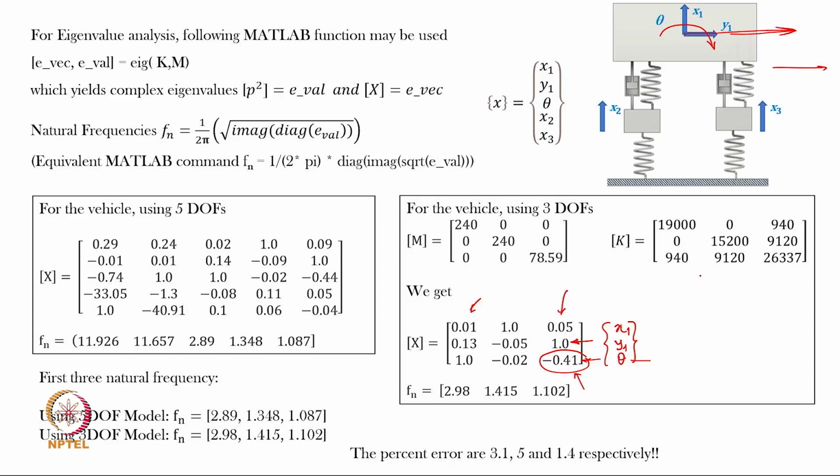I hope you recall that we discussed the mode shapes of a simple 2 degree of freedom system for one particular case when there were two masses connected like this, right. You remember that a spring here was K, this was K, this was 2K, this was M and this was M. So, what was the first mode? The first mode was defined like this. Both the masses were moving with the same amplitude in the same direction. That was your first mode 1 1.